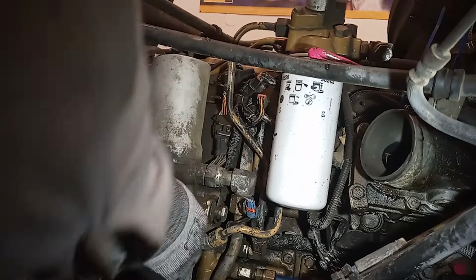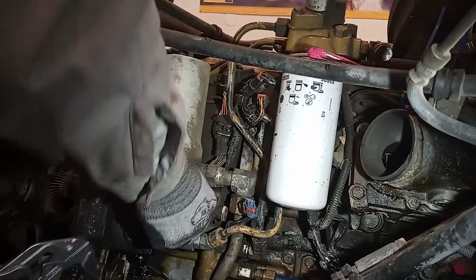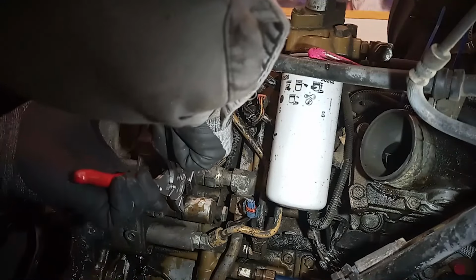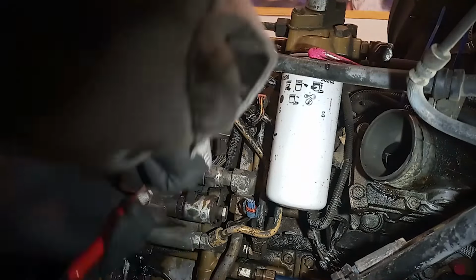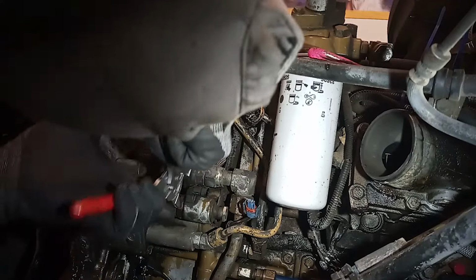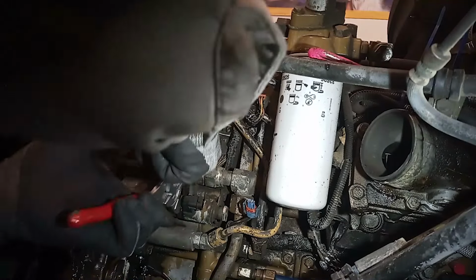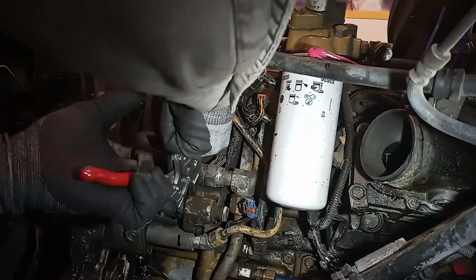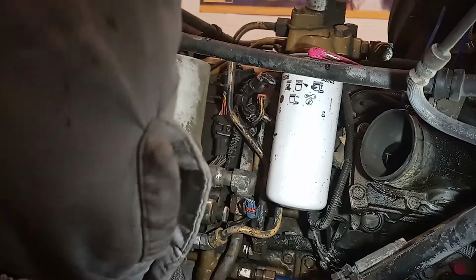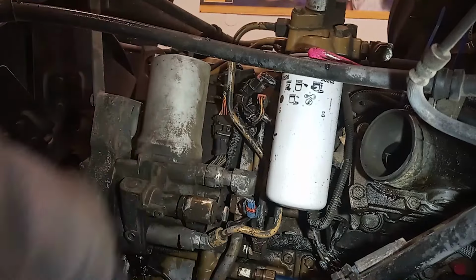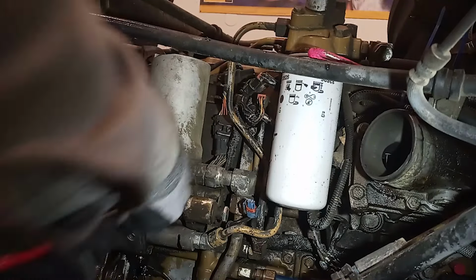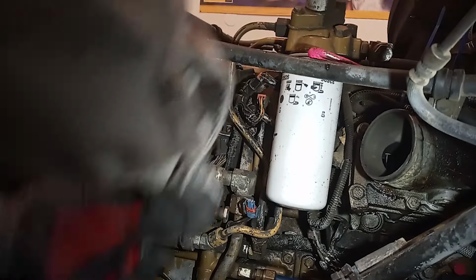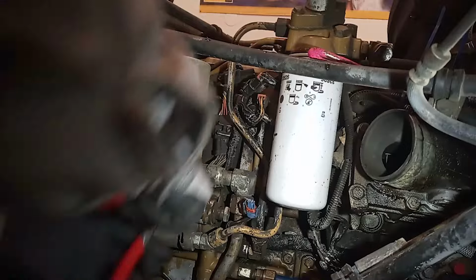Anyway, so what are we doing? Why are we pulling the solenoid off? It tested good. Well, we're pulling off the solenoid to put that dummy one in. And the reason we're putting the dummy one in is because if you put the dummy one in and then crank the engine, and it starts and it builds max pressure, like 4,000 psi, you know your injector seals are good, and you know your HEUI pump's good. If it still doesn't build pressure, then you've basically ruled out that the solenoid was the cause. Then you know there's something wrong with the pump or with the injectors.